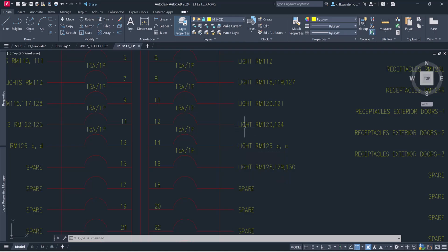Usually, in your building, you can put each room on its own breaker. Each lighting system can go on its own breaker, which really helps in terms of turning the lights off and closing off the electricity for that room. If you're challenged for space, you can double up or even triple up on some of these, but for the most part, you can just have one light on one fuse. So I'll show what that looks like on your own building.